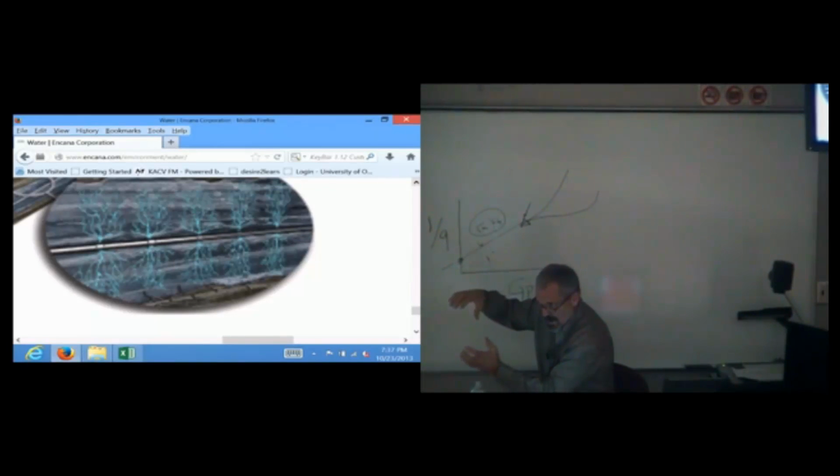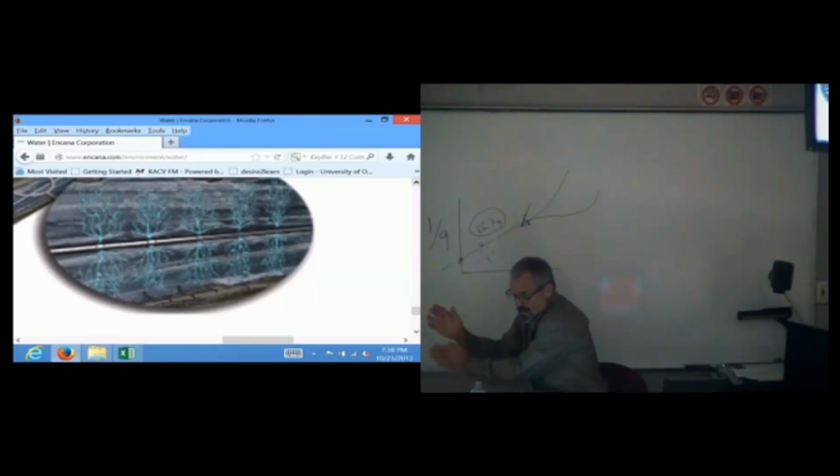This is what we do in the Bakken. And then we have ports that open up on mechanisms, and what we want to do is access and frack at places along the horizontal. Typically those fracks are 100 feet apart.